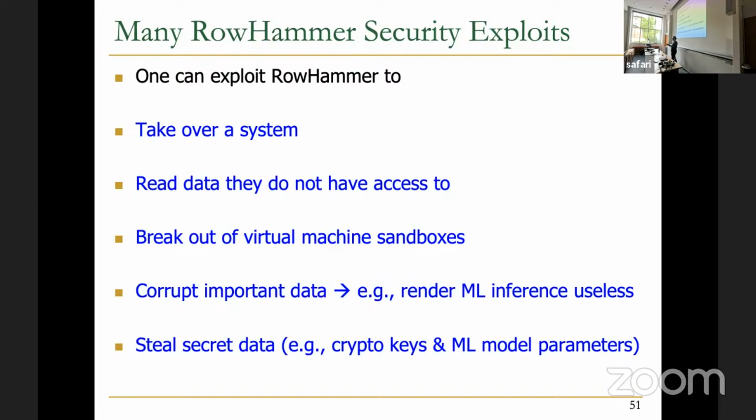They tried initially, and now they're trying harder. They tried initially, and we showed that their solutions are not good enough, not secure. Basically, we could induce bit flips in chips that they claimed are RowHammer free. They boldly claimed that, and that claim was broken. After that we started saying their names, basically, because I think they deserved it at that point. But right now, there's a lot more effort to solve it. In fact, the DDR5 standard introduces a much more rigorous solution. It's going to become harder and harder, but I believe there are still gaps. And we will discuss those gaps in the next lectures.